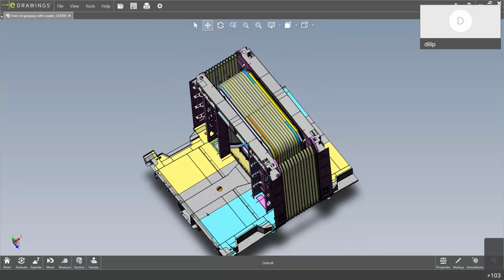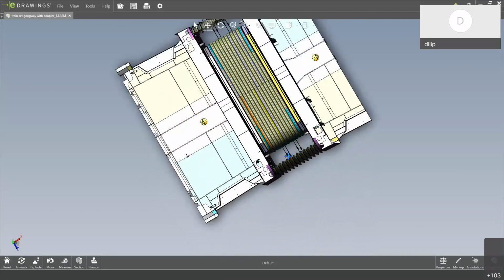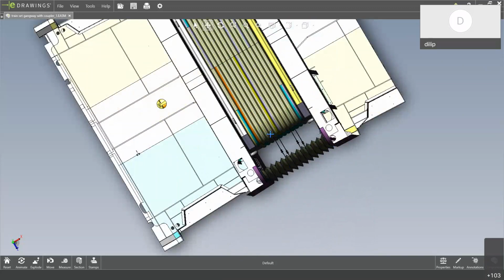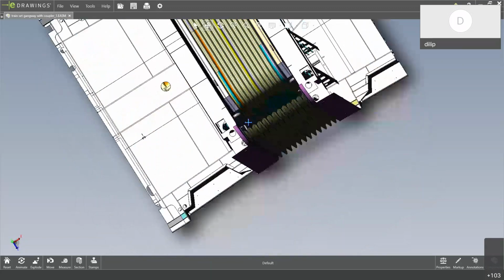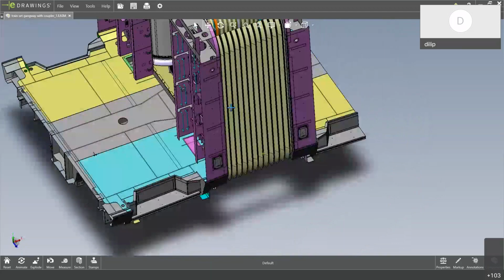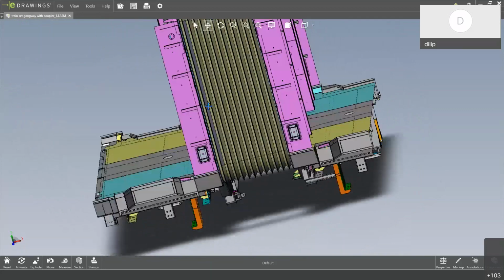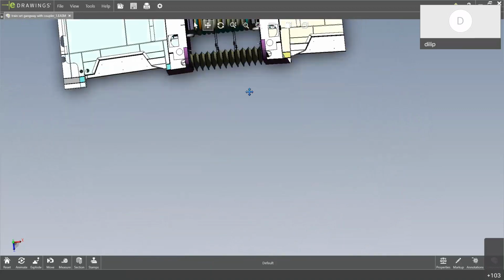And here we have the external fairing. The internal flexible arrangement and the external fairings are joined by plates, basically to support the weight and for better safety. In between these two assemblies, a lot of electrical cables will be going, that I have not shown. The external fairing will secure these cables so that nobody will access them from outside. Also, if you see the overall view, it will look quite better. It will show as a flushed train, and the aerodynamic forces will be less.